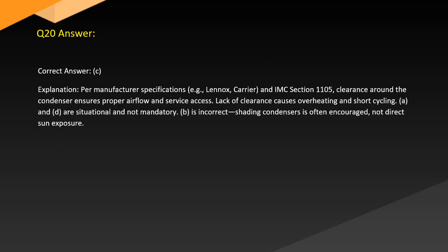Answer. Correct answer: C. Explanation. Per manufacturer specifications, e.g., Lennox, Carrier, and Inc., Section 1105, clearance around the condenser ensures proper airflow and service access. Lack of clearance causes overheating and short cycling. A and D are situational and not mandatory. B is incorrect. Shading condensers is often encouraged, not direct sun exposure.